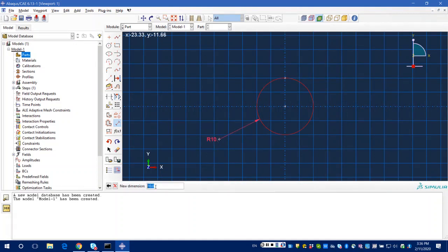The radius is shown here, but what I give you is 15 millimeter diameter, so you need to enter 7.5 millimeter, and then you just press the enter button. Right now you have this circle with a radius of 7.5 millimeter. Now I just say I have finished, cancel procedure.